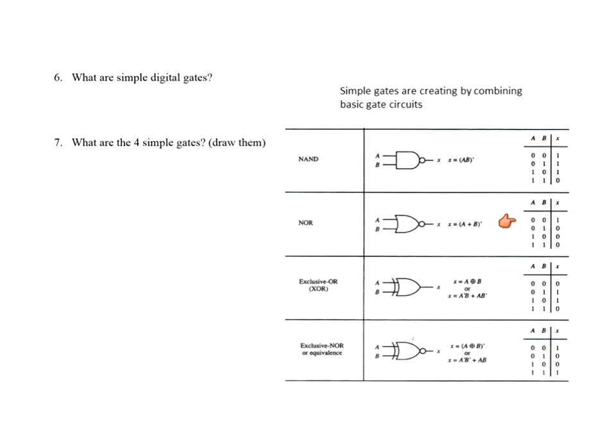Here's the truth table. And over here, the exclusive OR. This one's a little bit tricky. You can build an exclusive OR by putting other gates together. The exclusive OR looks like this, and there's not a NOT on the end. The exclusive NOR has a NOT on the end. Now, here's what's interesting about the exclusive OR. The only time you get a 1 out of the exclusive OR is when you have 2 different values on the input. If you have the same value on both inputs, you don't get anything out.